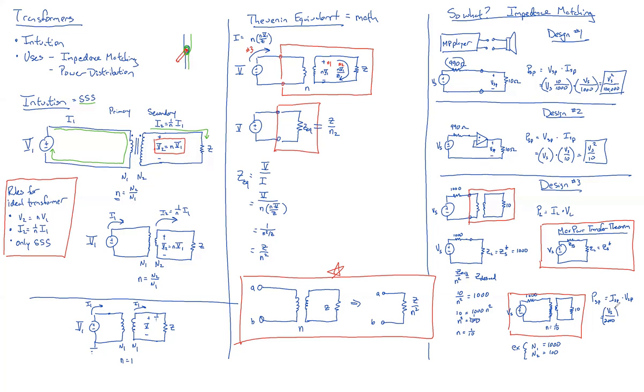The voltage is just half. And so now you've got Vs squared over 4,000 watts. Way better than Vs squared over 100,000. Not as good as Vs squared over 10, but it may be good enough for your applications that you still hear something and you don't have to worry about the batteries.